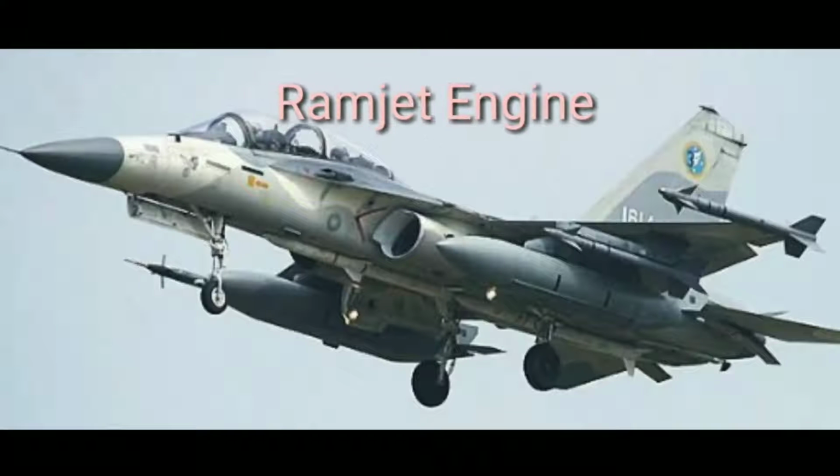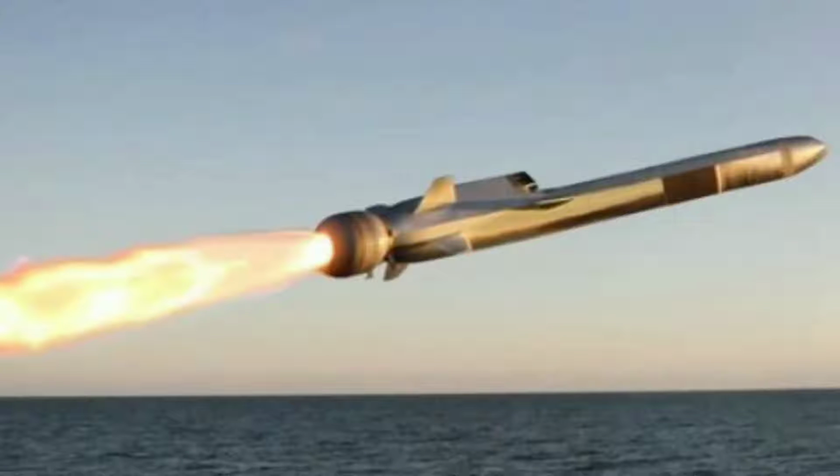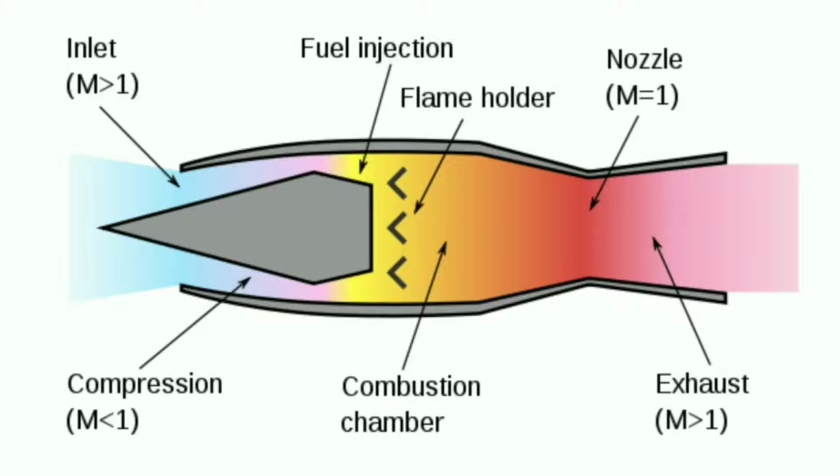The next is the ramjet engine, another type of air-breathing engine which requires the engine's forward motion to generate thrust. A ramjet cannot move an aircraft from standstill, but it works efficiently at supersonic speed at around Mach 3. That is why they are used mainly in missiles.